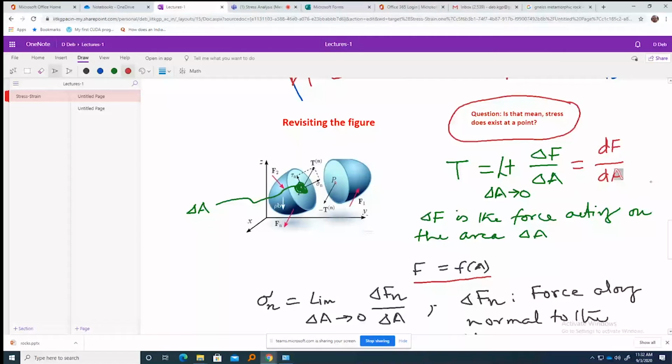Exactly. So if the pin is blunt on the top side where it is entering into the wall, then it will not go because the area is more. So it's basically force by area, which is stress, and that stress is exceeding the strength of that wall. So that's why it can go.